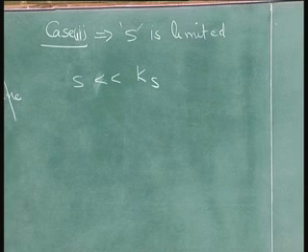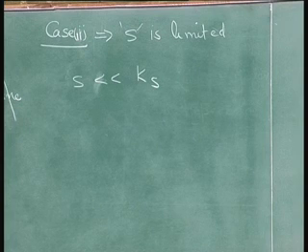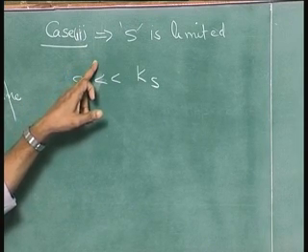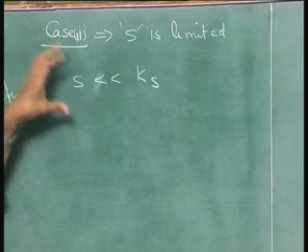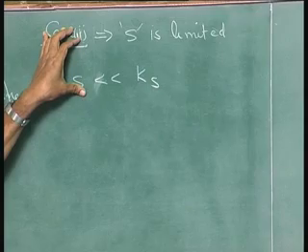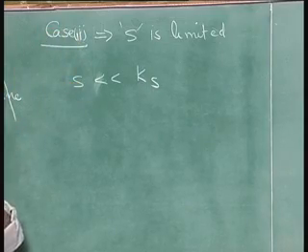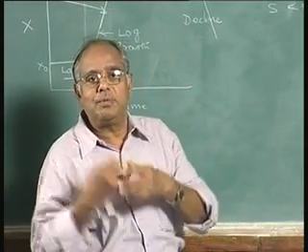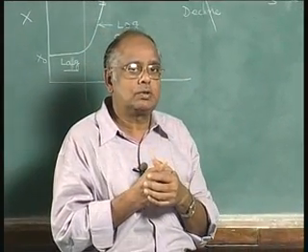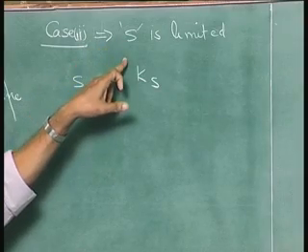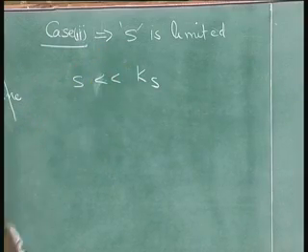In most cases in wastewater treatment plants, particularly in domestic wastewater treatment, we encounter this scenario. While in industrial wastewater, where the BOD is very, very high, we may get the first exponential growth phase. Here the food is limited, getting exhausted.